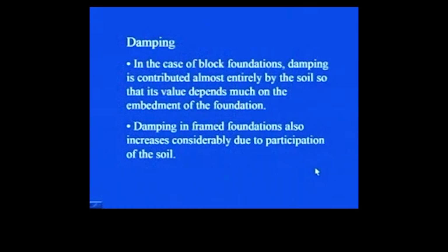In the case of block foundations, damping is contributed almost entirely by the soil, so its value depends much on the embedment of the foundation. You have seen that in a block foundation a concrete block is cast, and on top of that the mortar and the machine are mounted, and its mass is very heavy.